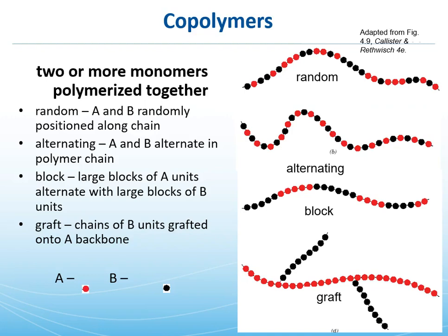Many of them are much more expensive than a single type of polymer, but they definitely have the potential for giving very, very unique properties that can't be achieved with just a melt blend of either one. I'll give an example before we quit today. So a random copolymer, and again this is a little bit like tacticity, is just the two polymers synthesized such that they're in any order and frequency along the main chain. Alternating means there is a particular order, usually AB, AB, basically like a stacking sequence.